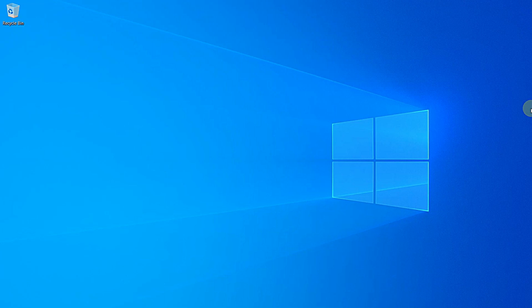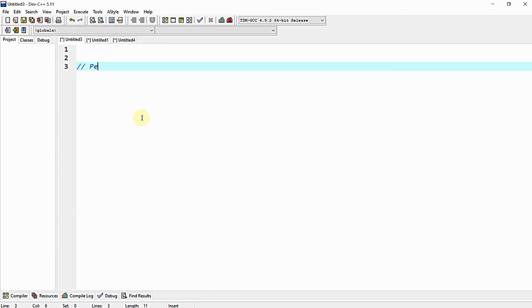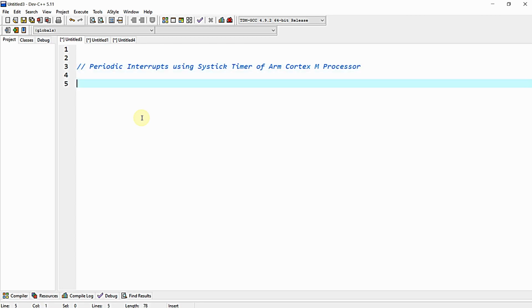As the first step, let me explain what I'm going to do in this video. We are going to implement periodic interrupts using the SysTick timer of the ARM Cortex-M processor.